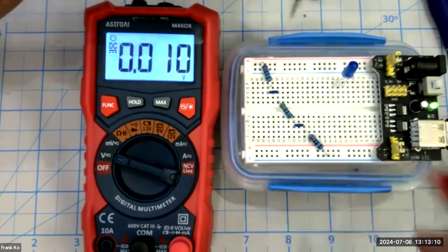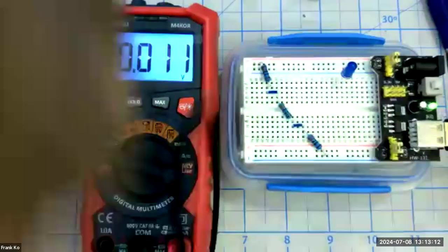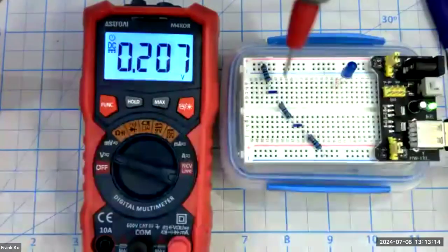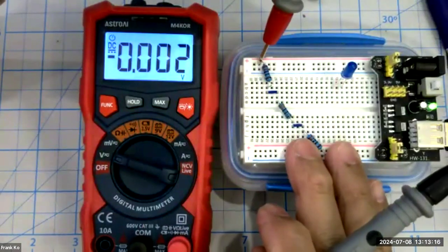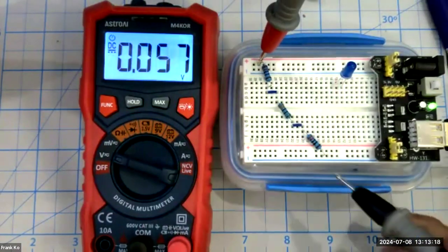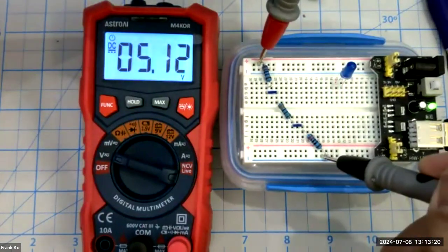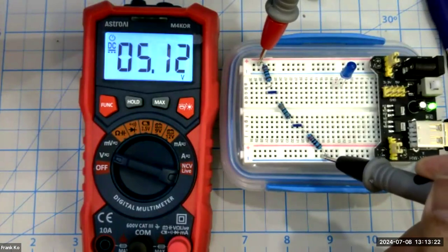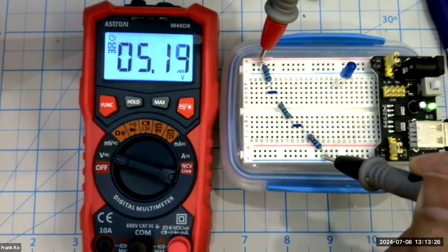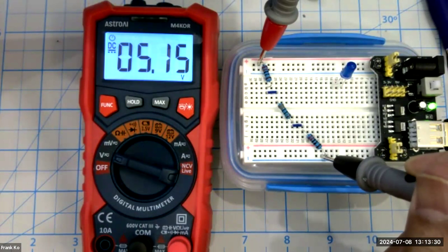Negative 5 volts just simply means I need to be mindful of where I'm putting my probes. So I'm going to flip the leads around. The red probe should be on the more positive side of the circuit, which is on the red rail, and the black probe should be on the more negative side of the circuit, which is the blue rail. If I use the correct polarity of the probes on the board for measuring voltage, I should get a nice positive, in this case, 5.15, 5.14 volts.